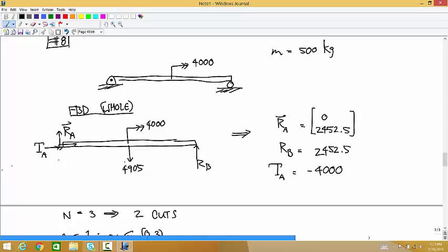But the point force that you use to represent a distributed load isn't a real thing. It's a mathematical thing that we use. So when you choose how many cuts to make, be sure you're looking at the real loads, as distributed loads. Don't do it looking at the picture like this one where the weight or distributed loads are represented as point forces, or you'll have extra cuts. And the answers will be wrong.